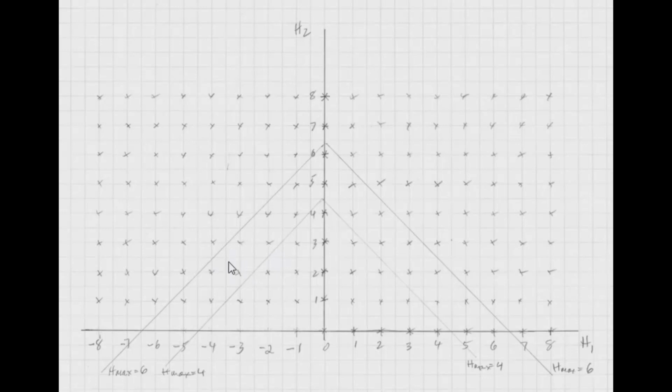Another thing you have to be careful about is the frequency spacing in two-tone problems. You can't say I want a 5 gigahertz excitation and 10 kilohertz spacing. It just won't work because the Fourier transform won't resolve those small differences. You really need to keep those fairly far apart. Another thing you need to do with the frequency spacing is make sure that a harmonic of one tone does not land on top of a harmonic of another tone, because the Fourier transforms really don't like that, and the harmonic balance process doesn't either. So be careful with that.